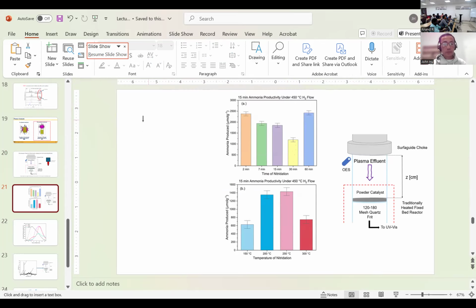Sir, in plasma generation, can I ask one question? Go ahead. I encourage you to ask questions instead of me just talking. What's the question? Sir, here you mentioned that with the aid of argon, we can initiate the plasma, and later combine that with the nitrogen. Actually, we are facing one problem in our laboratory. Even by injecting argon, if the pressure is more than atmospheric, it is very difficult to generate plasma.